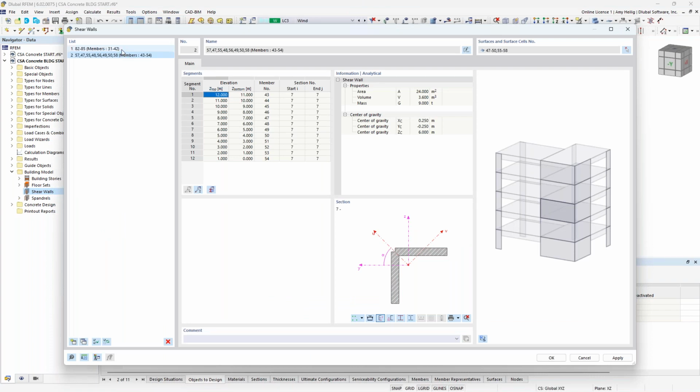Now we can take the result beam from this first set of shear walls and actually design the reinforcement in the concrete design add-on as a typical member. And I will show you that shortly with the spandrels. But for the shear walls here that are at a 90-degree angle, it's not quite ready in development that we can also design the reinforcement. We can only consider one single plane right now, but this is still going to be helpful in the analysis output in just a minute.